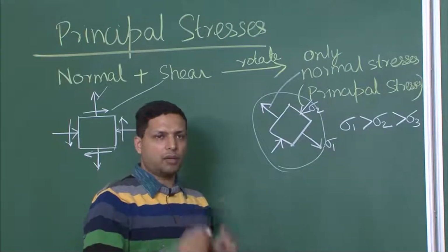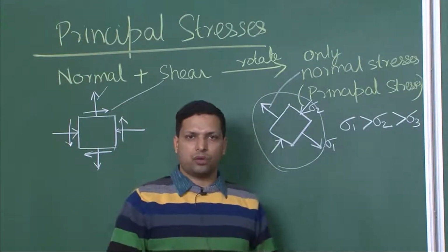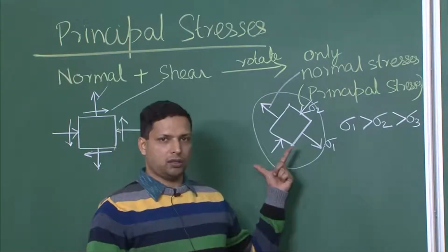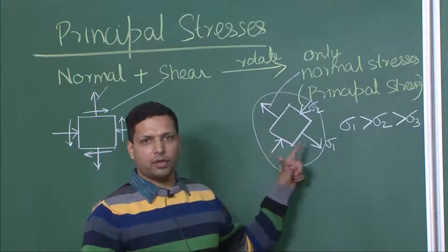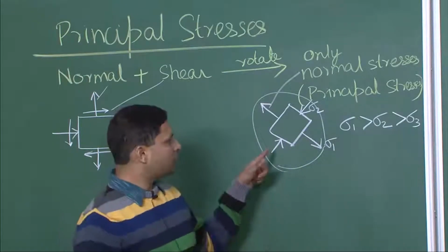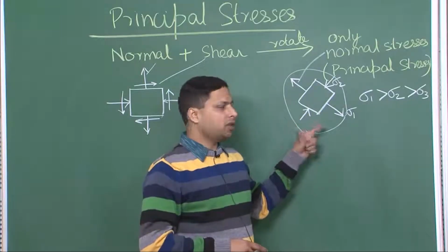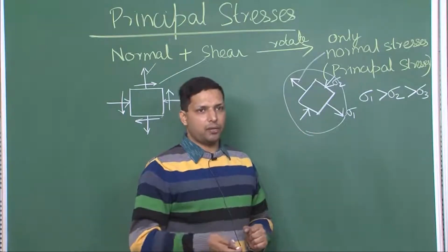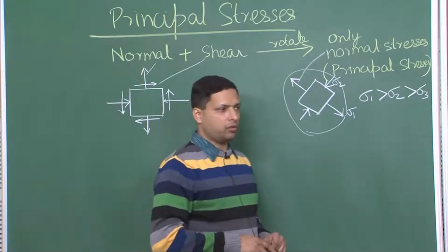It is at that particular angle, and you will be able to see when we use what is called the Mohr circle construction, that there exists a particular rotation for which you have no shear stresses and only normal stresses. You will also see that in general you cannot say there will be a position where there are only shear stresses and no normal stresses. In particular cases it can be, but in general that will not be true.